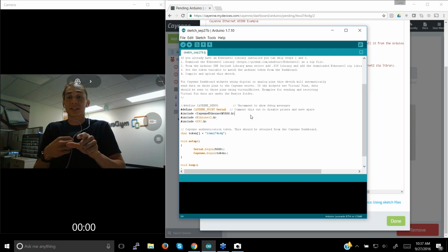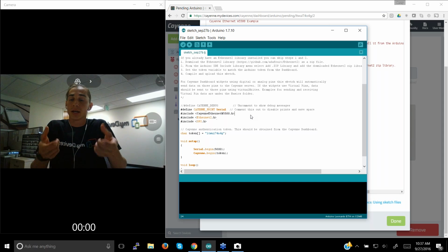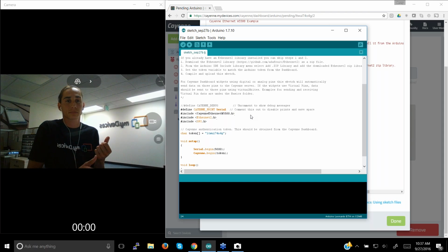And one other thing to add, scheduling. Scheduling actually runs locally on the Pi, because the Pi has storage and an OS. We can store the scheduled events locally on the Pi. So let's say your Pi loses connectivity for whatever reason, and you have it scheduled to turn on a light or open a door lock, that will still work regardless of internet connection. So that's pretty cool and pretty important. You don't want to be locked out if you lose internet connection.